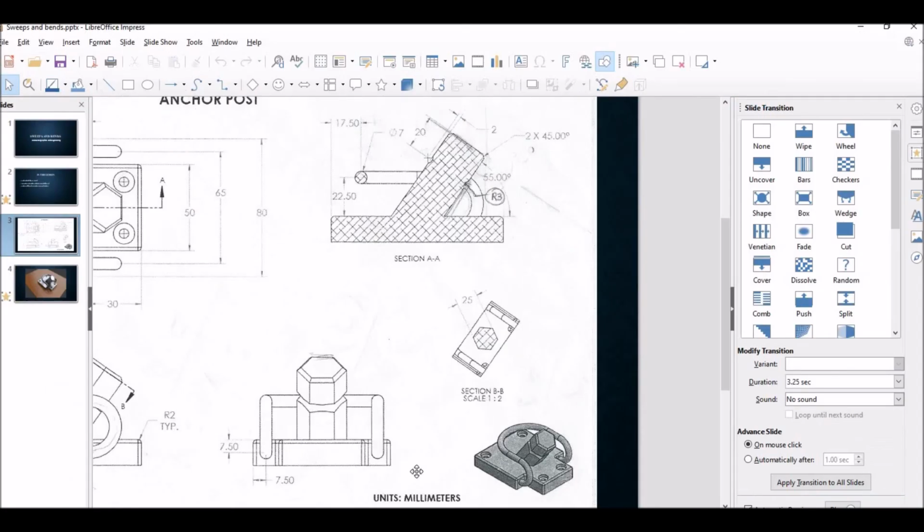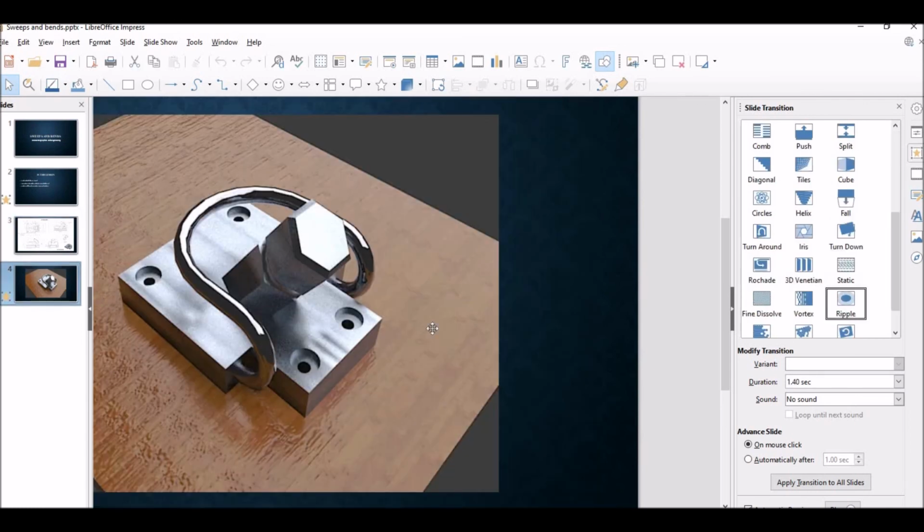The last but not least, we need to do this part. This video will be next. It's not that bad. It's basically using the Follow Me tool. We're going to make a line that follows this exact same shape. Make a circle here and then do the Follow Me tool and then union it at the end so that it will look like this. Nice and pretty.